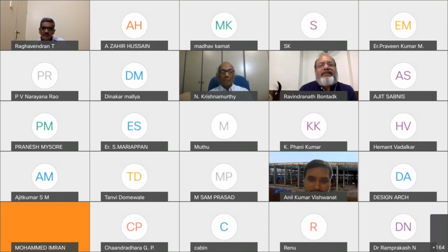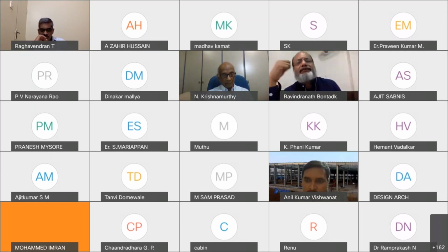So, my first question is regarding this. Sir, you mentioned SP6 in your presentation. But most of the sections in SP6 are not satisfying the slenderness criteria of the Indian code. We have not yet received any update on SP6. And the plastic properties mentioned in the IS code are only for specific sections, so this was not implemented in SP6 for all the other sections shown there.